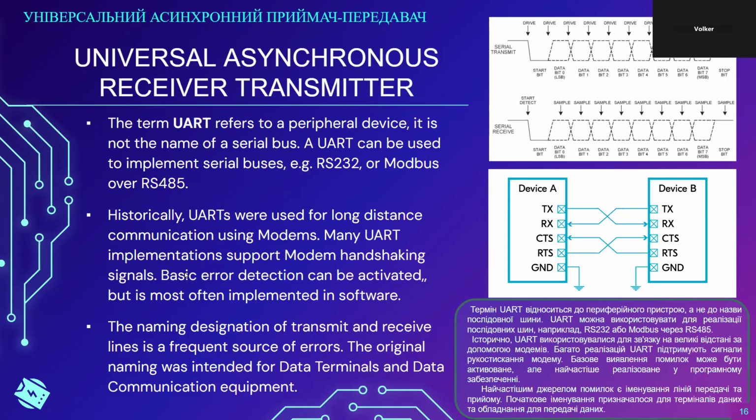Buses like Modbus do more in software. So the features of bus turnaround and error correction in Modbus implementations are done in software. So there is a significant amount of software effort required besides just loading up a UART with data.